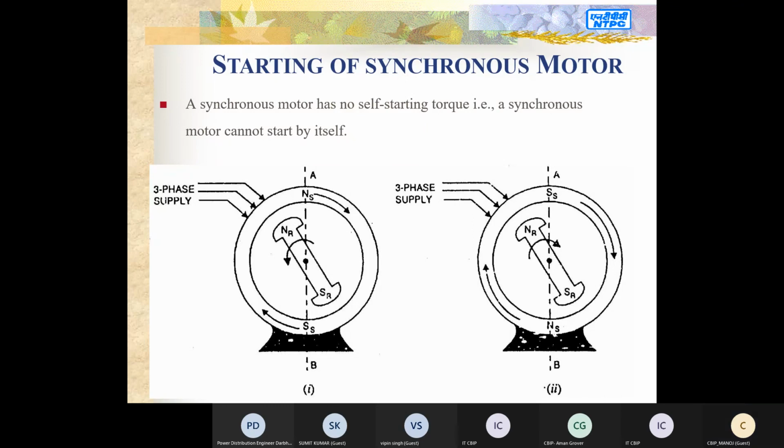In the case of a synchronous motor, we also use damper winding for reducing the oscillation. Yes, sir. It is another way to nullify the hunting or oscillation. There are other means of starting synchronous motors too, like starting the synchronous motor like an induction motor by giving another winding in the rotor.